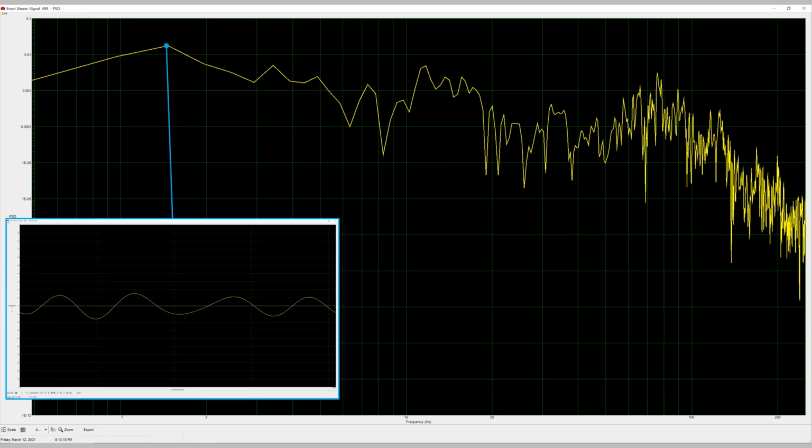Well, there's that less than 1 hertz frequency content that, through filtering or through the Fourier transform, we can say, okay, show me the content of, basically, 1.5 hertz. And once we generate that and we do some averaging, the average intensity of the signal across this time domain window, we plot it. We say, okay, I'll pull that out, I'll dissect and find out what kind of 1.5 hertz energy is there, come up with an average intensity, which computers do for you, and then I plot it on the PSD.